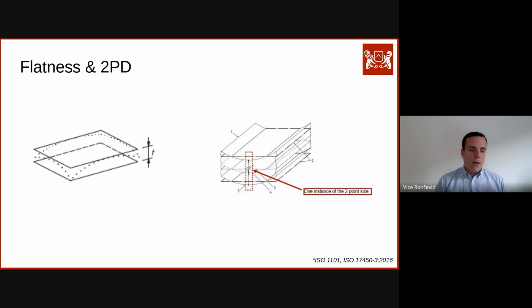That means that on that surface where we have this flatness tolerance defined, if you sample a plane, which is sandwiched in between these two ideal planes, this sampled measured plane has to be fully contained inside two ideal planes that are 0.2 millimeters apart. That is essentially the essence of the flatness tolerance.